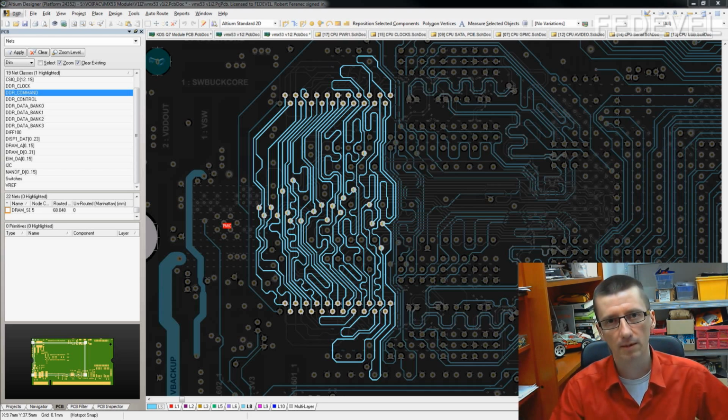The signal flies differently on the top and bottom layer and in the middle of the PCB, in the speed and all the other things which you don't need to know. All you need to know is use the same topology for buses and same groups. You don't have this kind of problems.